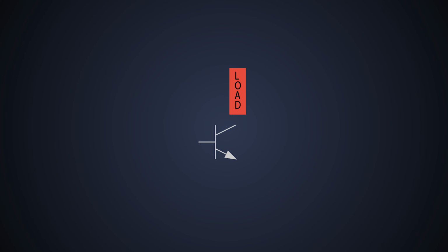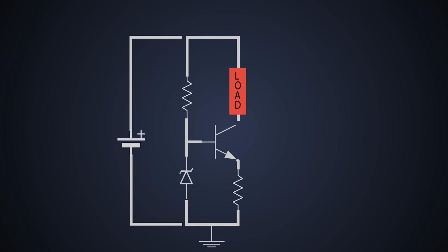First option to make a very cheap and easy constant regulator is to add a Zener diode and a couple of resistors. We can add a Zener diode which provides constant voltage to the base of the transistor, a current limiting resistor to this Zener diode, and a resistor between ground and emitter of the transistor. This current limiting resistor provides required current to the Zener diode, and it provides voltage to the base of BJT. The output voltage of the Zener diode remains constant.